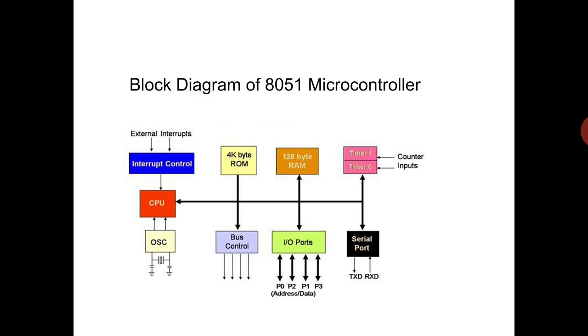Timer 2 can be programmed to decide the baud rate for serial data transfer. The SCON, SBUF, and PCON registers along with the TMOD register are the special function registers used for establishing serial data communication between the microcontroller and the outside world.